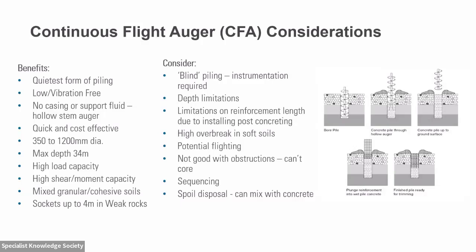The second key point on this is that you finish the pile at the ground level, at the level you're piling from. So there are many instances where you're piling from a level and you want to excavate a basement or excavate down below that for one reason or another to get down to your actual construction level of your pile, but you need your concrete in CFA to finish at ground level. So you'd have to break that pile down to the level that you need to get to. So those considerations just need to be made when you're choosing a pile foundation at a design case.